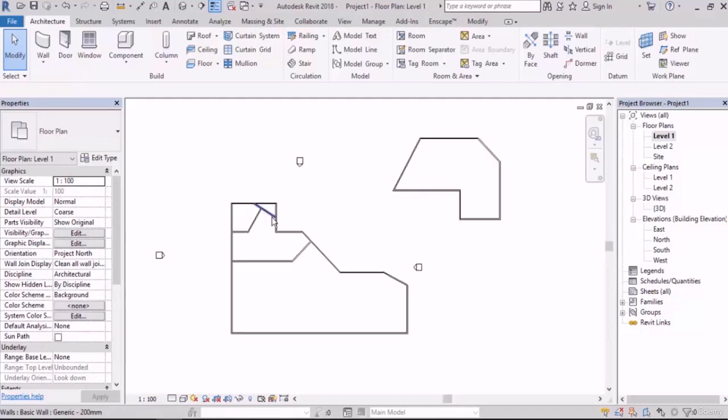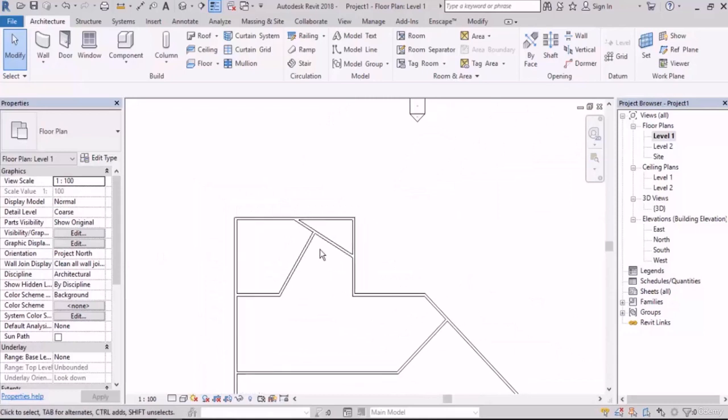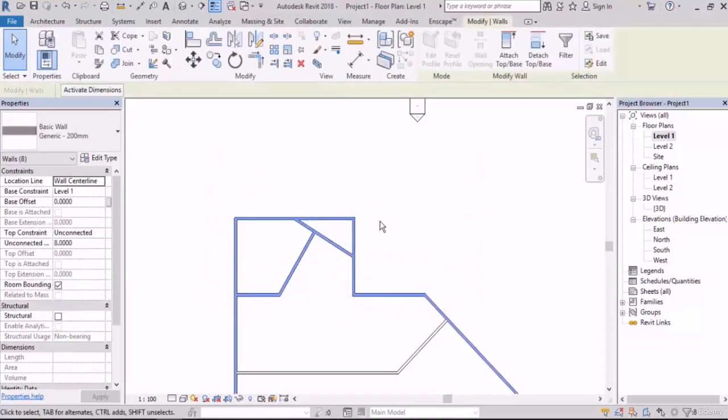The first kind is to open a rectangle from left to right. But in what way can we select? As you can see now, it doesn't select anything. If one object is completely inside this rectangle, then it will be selected. But if I open it from right to left, it's just enough to get close to that object and it will select it. If even a small part of it is in that window, it will select it.